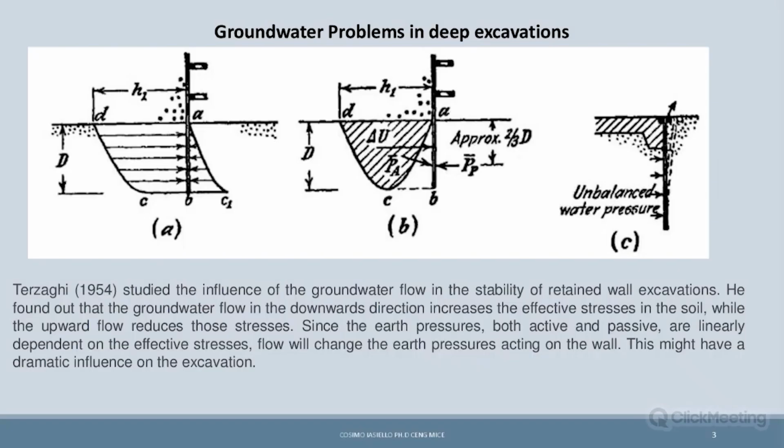So, regarding groundwater problems in deep excavation, I'm going to go very quickly. I'm sure everyone in this webinar knows the problem with water. If this is our excavation, and here we have our level of props, and here we have the pressure acting on the structure, this is affecting directly the effective stress in active and passive conditions.